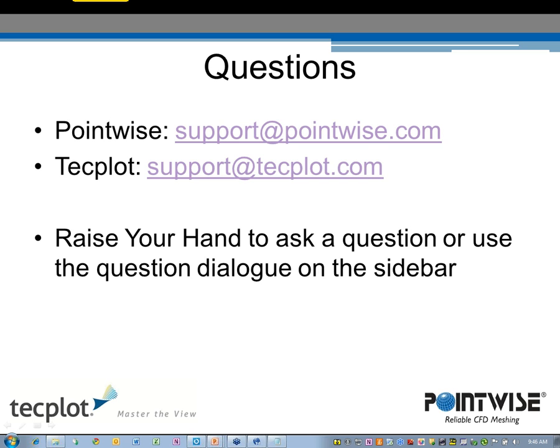Is the value of 0.4 at tip speed ratio 1 looked like something that I would not expect. Any comments? Yeah. Again, this was an optimization, so we were optimizing for that tip speed ratio. So it's not entirely uncommon that you could get an efficiency that high if you were optimizing the blade shape. But again, yes, I've seen similar things in literature, and this is why going into 3D and actually analyzing the performance of these high solidity rotors at these low tip speed ratios would probably produce a more accurate coefficient of performance.